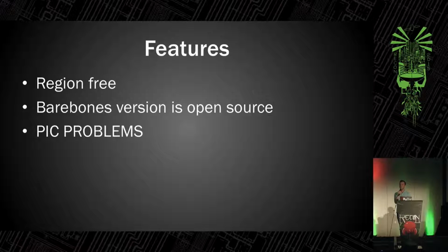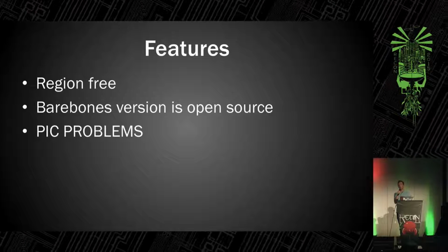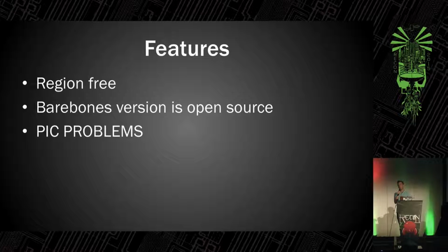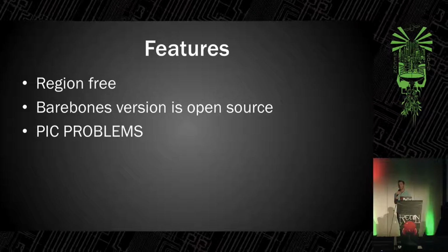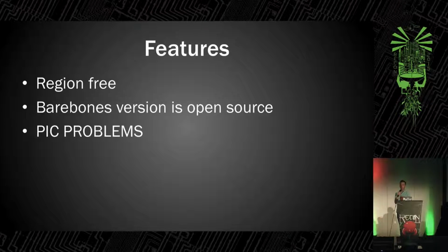That didn't work out. Luckily, Microchip makes a pin-compatible part to the one we originally spec'd, and it has an internal 4x PLL. So we were able to get around that. So I guess you win some, you lose some with PIC.